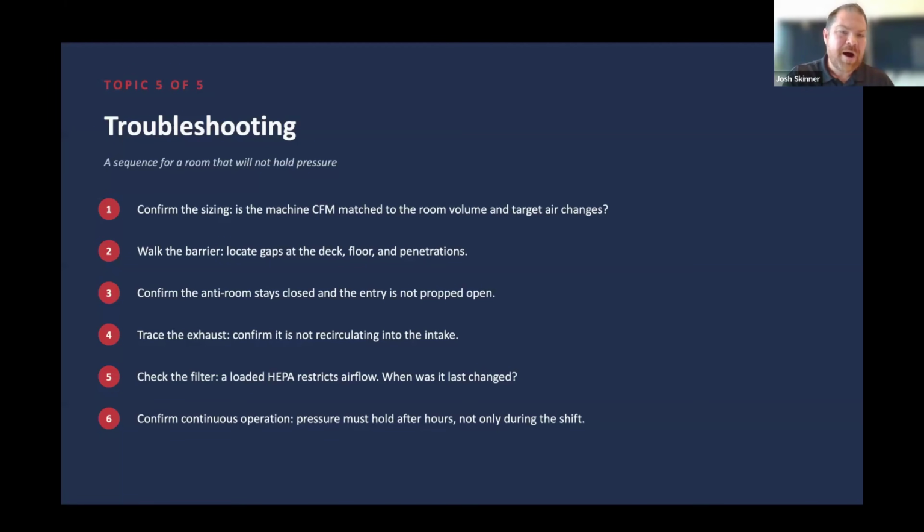The one thing that often gets misunderstood or overlooked is the system you're using to monitor whether you're in negative. Did you set it up correctly? You talked about the hose getting clogged earlier. Is the machine put on accurately? So it's one that gets missed. These machines are not a Bible. If they're set up right, they're going to work great, no matter what machine you use. But did you set it up right in the first place? Did someone pull the hose loose? All of those things. Start from the beginning and walk from step one all the way through. You're going to find it usually halfway through that process, going down each one.